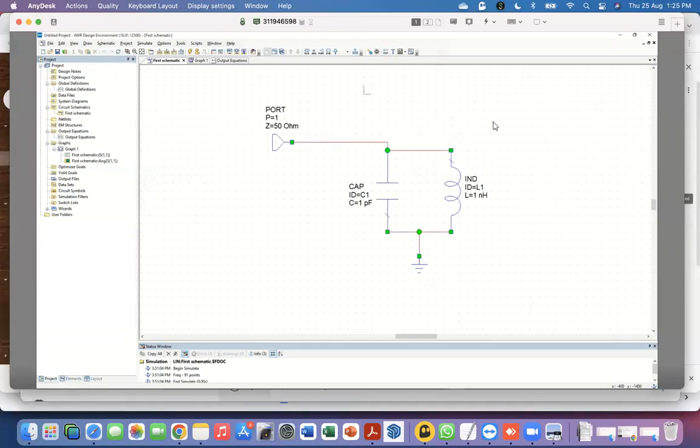Yeah, maybe some of you have already computed this number on the back, but here's another little Microwave Office thing for you to see. I can do a calculation here. Let me define f res equal to 1 over square root of 1e minus 9, that's the inductance, multiplied by 1e minus 12, that's the capacitance, and then the whole thing divided by 2 into pi, let's say 3.1415926.